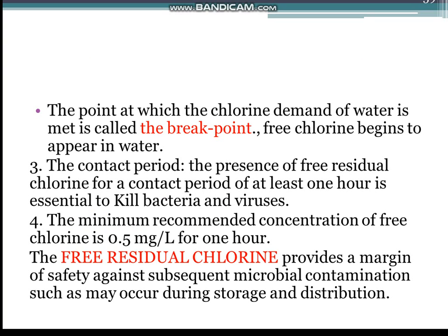In other words, it is the amount of chlorine that is needed to destroy bacteria and to oxidize all the organic matter and ammoniacal substances present in the water. The point at which the chlorine demand of the water is met is called the break point. If further chlorine is added beyond the break point, free chlorine begins to appear in the water.